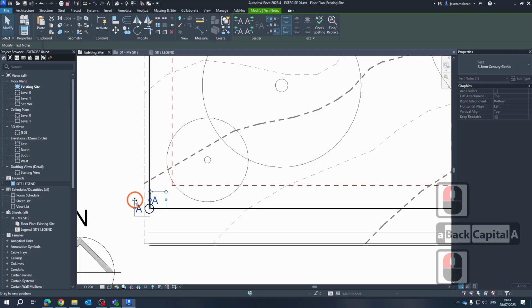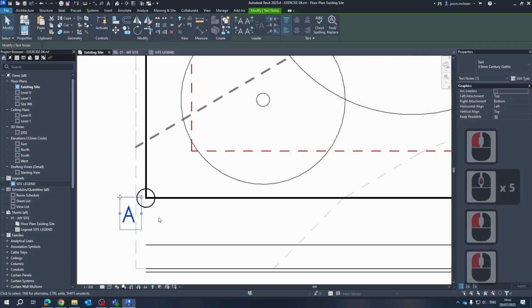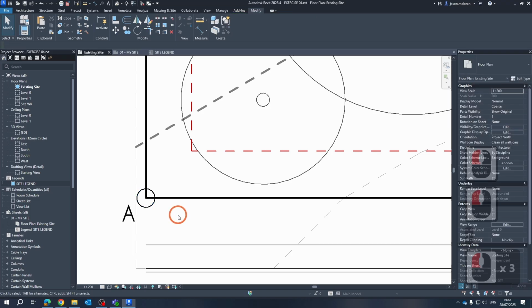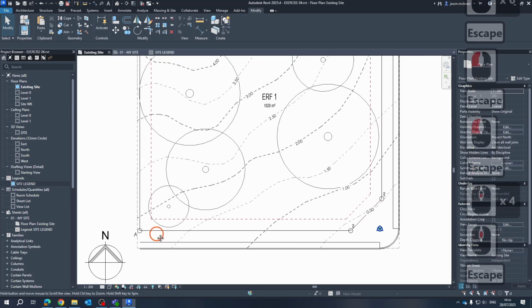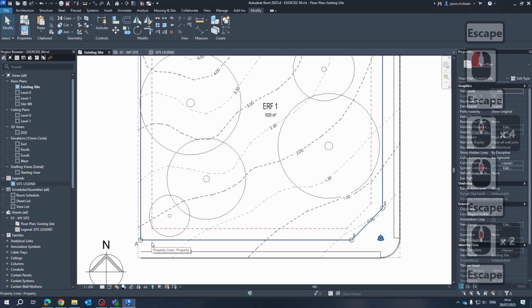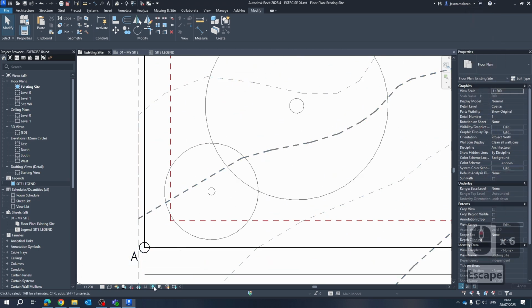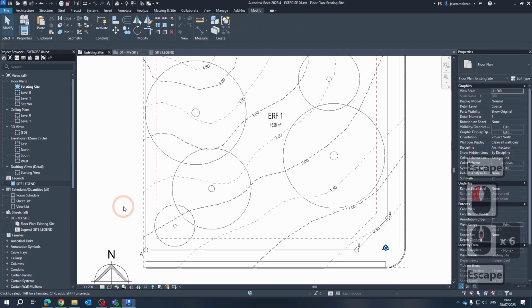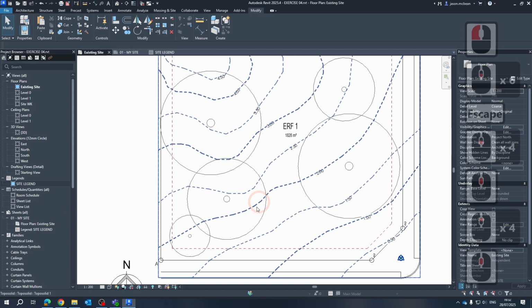Okay, move the text to the right location. This is why we don't use family sometimes, just because some families where the text or the text label is located, you can't move it. It gets very difficult to work with, and you've got to write parameters. It's just not ideal for how we represent our site plan. So sometimes we have to use 2D elements to represent certain things. Okay, so I'm going to quickly pause the video and go and rename the rest of these.